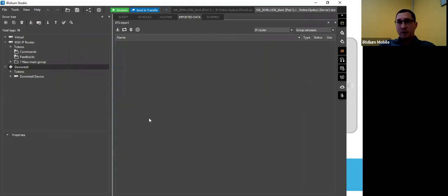Our server and your panel have a connection at the IP level, which is very fast, I mean Wi-Fi and LAN, so it will be very fast. But if we have a connection to the KNX bus, it's always low speed, because all telegrams should be transferred from the IP level to the KNX level, and actually it's a very low speed. Okay, that was about how we can make a new project from the panel.